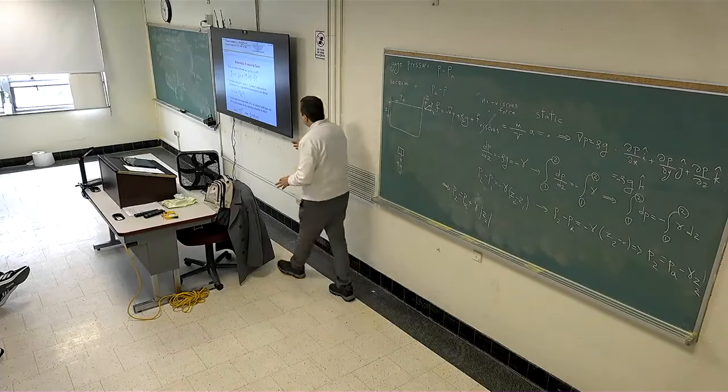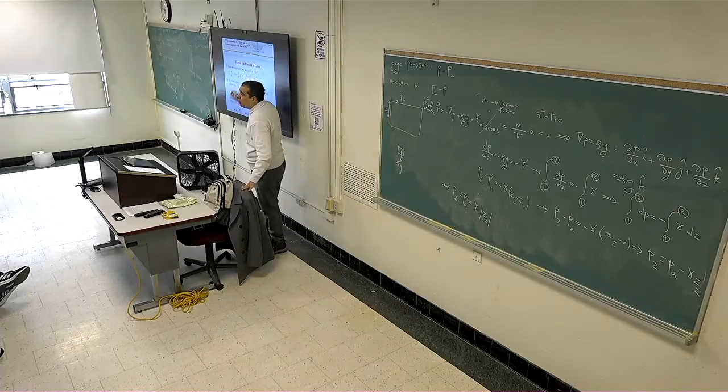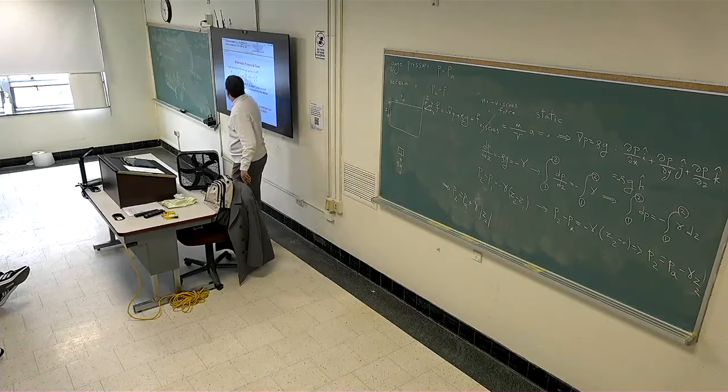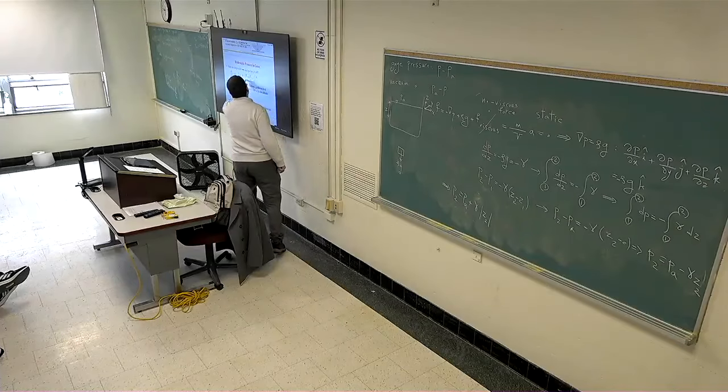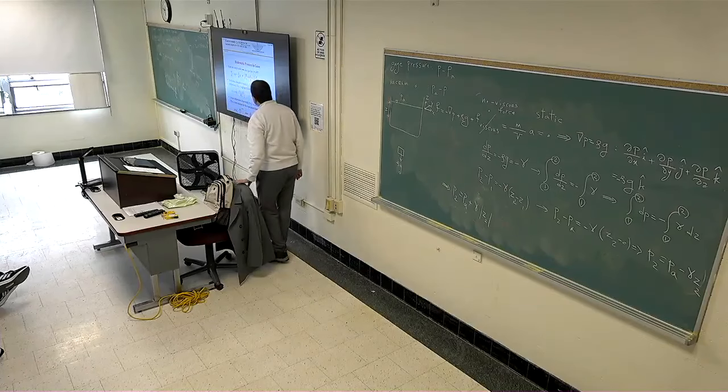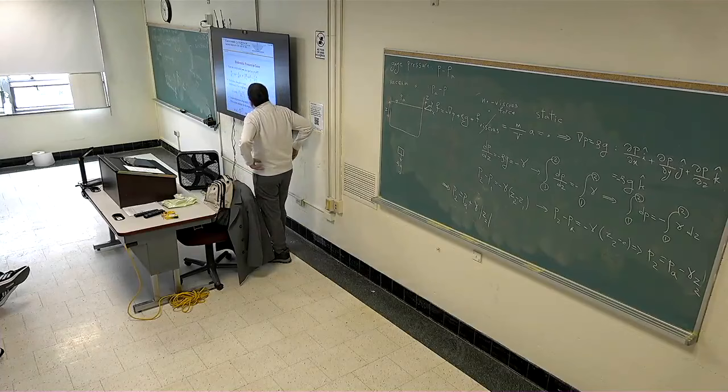But for gases, rho and P are connected. So instead of rho, I put P over RT from the equation of state. And then integrate dP over P, and dZ over T times minus g over R. So, it is our equation for gases. The left side is ln P2 over P1. The right side is this equation.